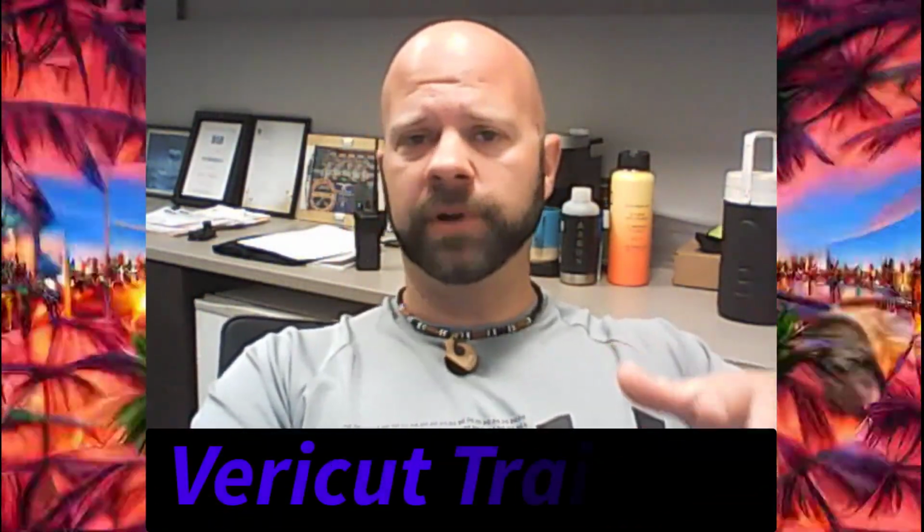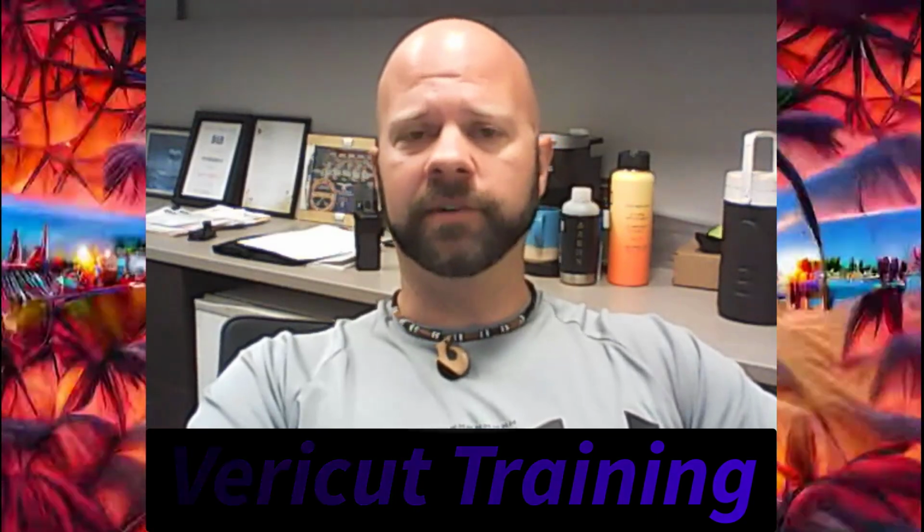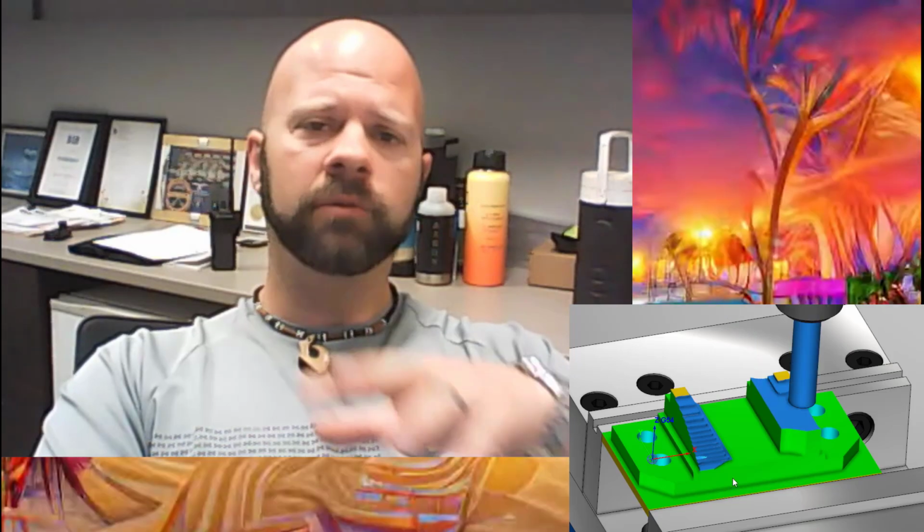So what we've watched in our previous videos is how to make a Vericut file, bring in our vises, our materials, so on and so forth. What we're going to do today is I'm going to show you how to take a finished Op1, convert it into its own model, and then we're going to bring it into an Op2 environment, and then we're going to run our Op2 on the Op1 cut stock. That way we can see exactly what we're going to get when we run our programs on the machine. So let's get to it.